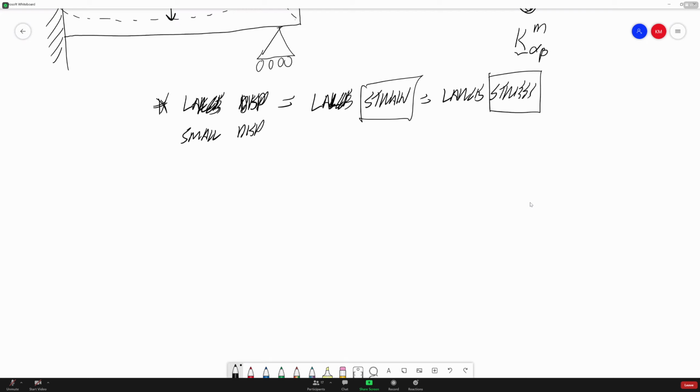But we will see the stiffness matrix and global stiffness matrix, and then we'll break it down into an element stiffness matrix. 3 of them actually, 3 integrands, and then in order to solve the problem completely, you would apply the appropriate Gaussian integration rule to get your final answer.